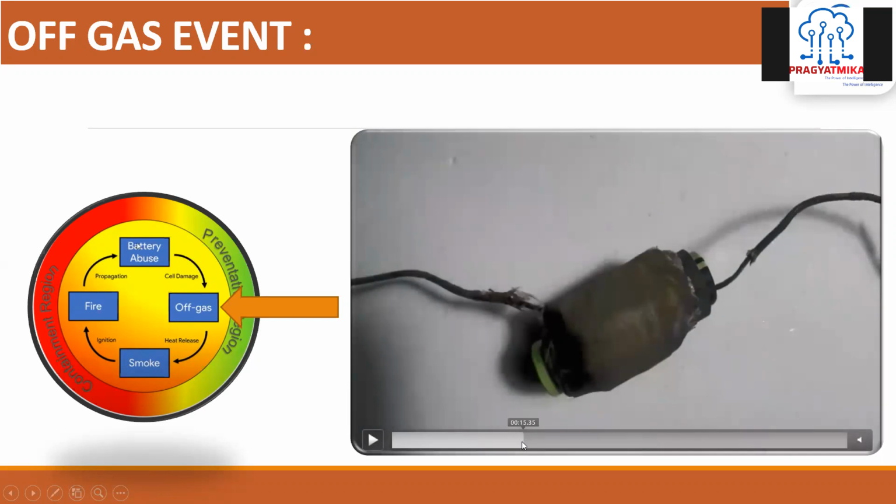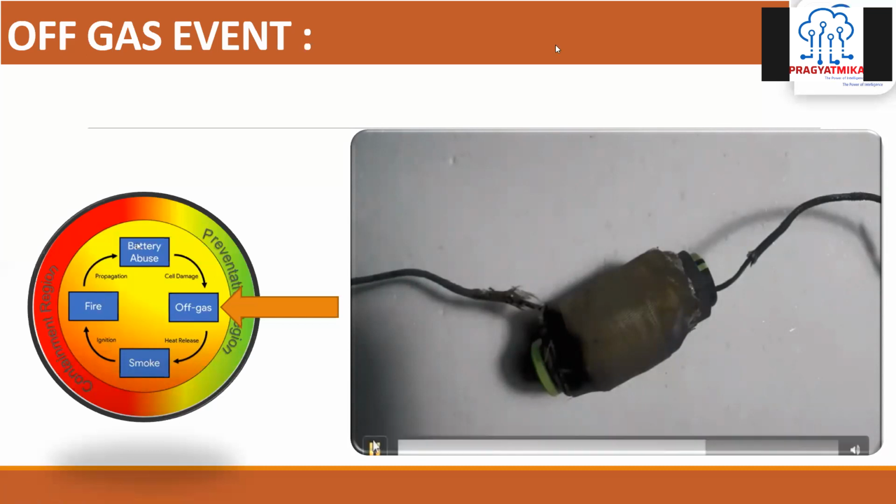Once, just see this stage. As you can see, there is a certain vibration in the cell, and some of the materials have extruded out. So it has actually broken the cell capping, and the internal oxide material has come into direct contact with the air oxygen, which would further lead to the catching of fire. So at this time, when the gases were bulging inside the cell, if that could be detected within the pack, we can have some sort of relief.